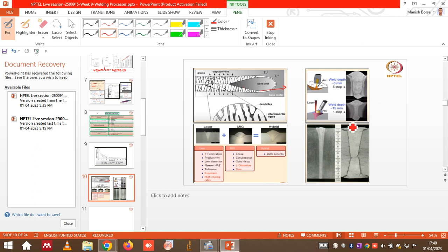Okay, but in the other conventional processes like MIG, the efficiency of the welding process is low, and heat power density is also low. But those processes are quite economical. So there are some attempts, like the combination of laser plus MIG welding, that can give higher depth of penetration as well as a wider bead, so that the load won't be concentrated on a very narrow area.